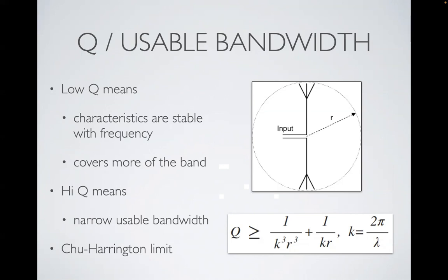So if you have, for example, one of these so-called magnetic loops where you have to tune the thing, you'll find that the smaller it is relative to the wavelength, the more narrow banded it is, to the point where at some point you can't even modulate it. So that's something you have to be aware of. You can shrink an antenna structure to a point, but at some point it becomes not a useful antenna anymore.